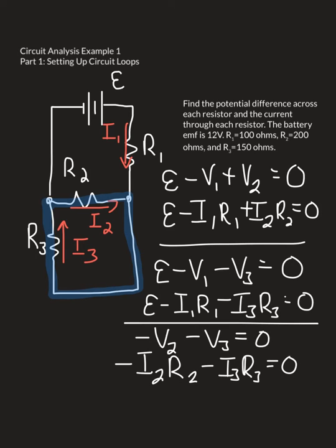And already there's some hint that I've chosen something that's not quite right, because we have two negative quantities and we're putting them together to equal 0. So one of these quantities actually needs to be positive and the other negative in order to sum them and get 0. But don't worry about it. Like I said, when we solve for this, we're going to discover that I2 comes out of these equations as a negative current, and the negative sign will just tell us that that's the arrow that was pointing the opposite direction from the actual direction of the current. It's not a big deal.